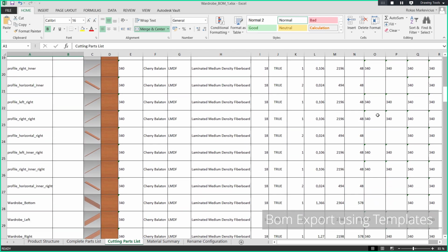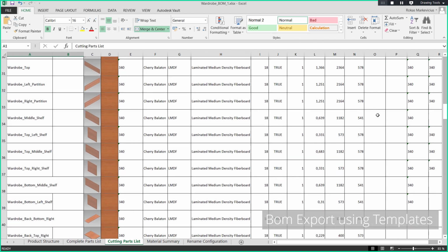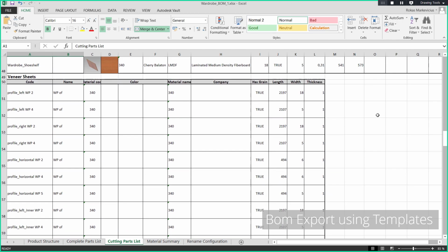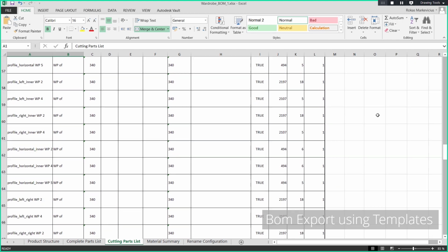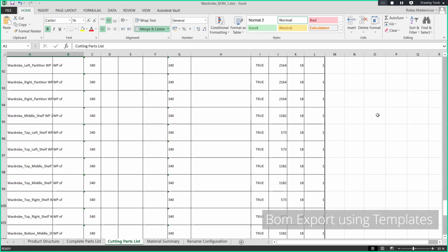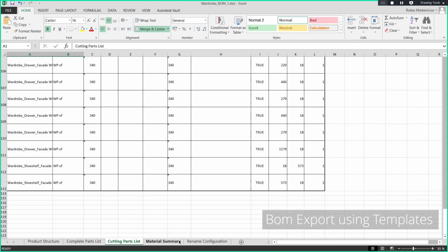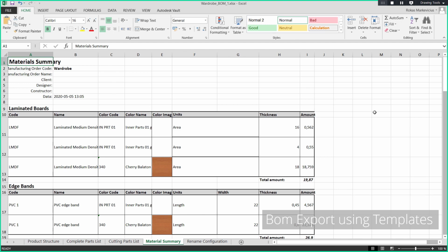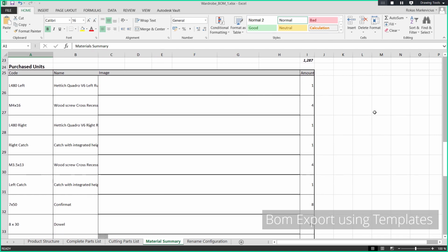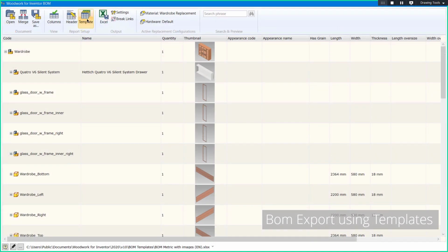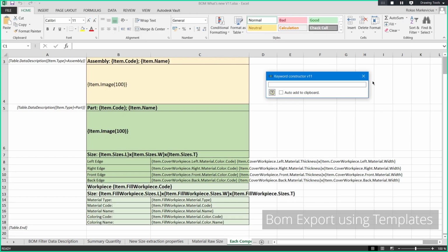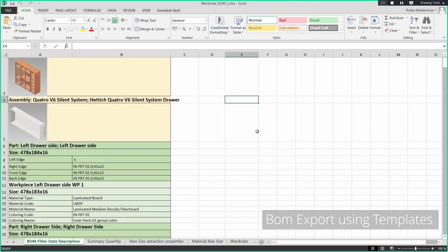You can use not only the keywords, you can use formulas on top of that. You can even use Excel scripts to make it work as you expected. For instance, if the length of the part is bigger than some reasonable value, you can use a script which will show a warning message that this part is too big. Or you can take the material summary like we see here, with the rough amount of material, then multiply it by a prime cost to estimate how much it will cost more or less, even before generating and nesting, because the total price, of course, will include the nesting.